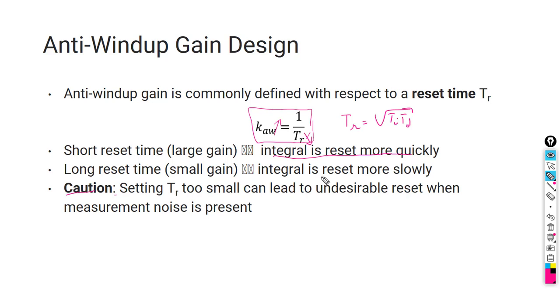But if you have a derivative term, you remember one time we told you that the proportional term also amplifies the noise. So if you have noise on the measurement, then having high gain will amplify the noise, because the proportional effect also amplifies it. So it's not desirable if you have a derivative in use. If you don't have a derivative, take a large gain.